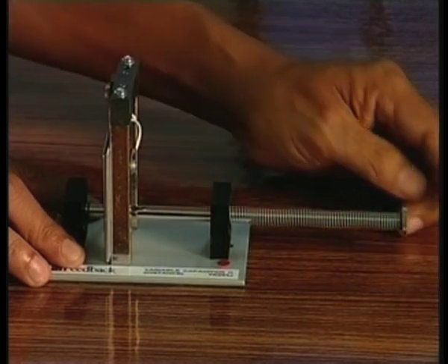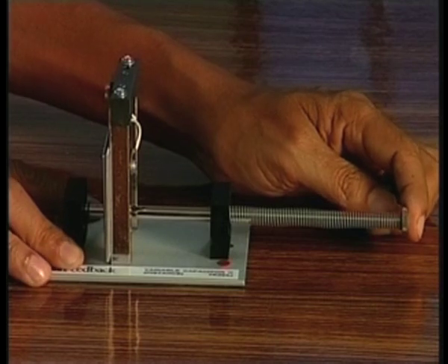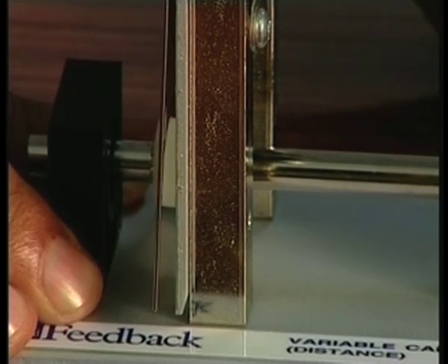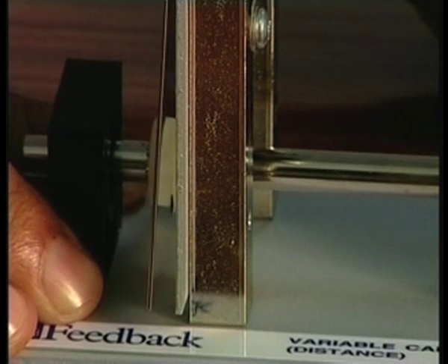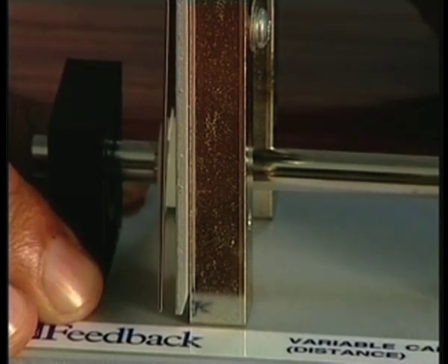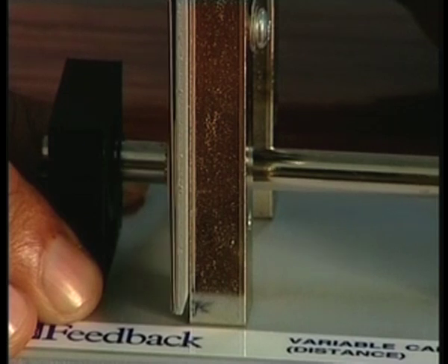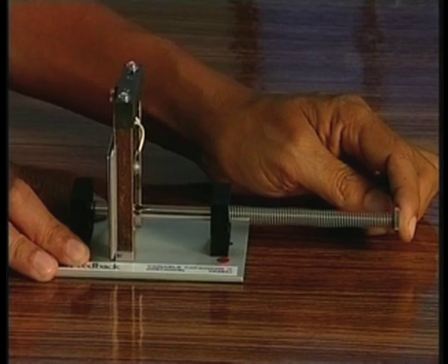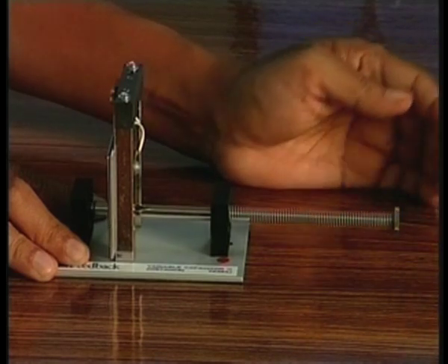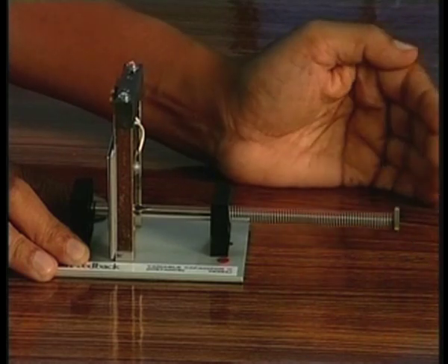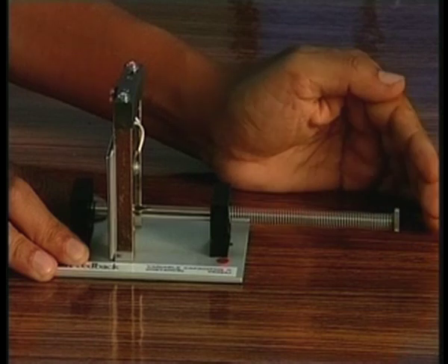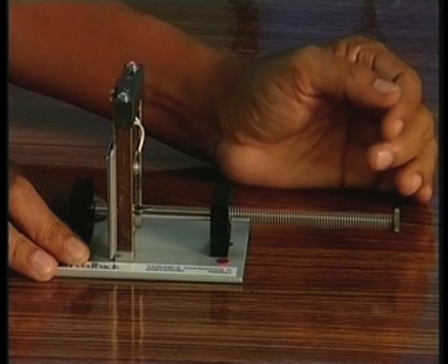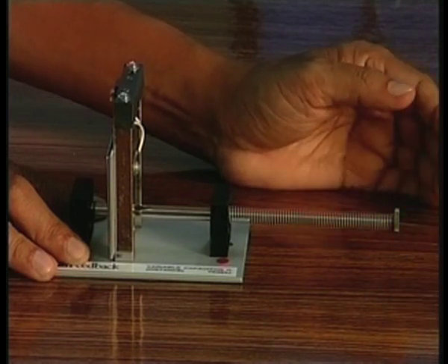You see, if you make the displacement here, the separation between the capacitor plates changes. So obviously, if the separation changes, the capacitance value also will change. So if you put it in a bridge, the bridge unbalanced output also will change. That bridge unbalanced output can be calibrated in terms of the displacement, because ultimately we are not measuring the capacitance, we want to measure the displacement, which is our input, that is converted to a variation of the capacitance, and ultimately which will give you some unbalanced voltage. These are other applications of the displacement sensor based on capacitance.